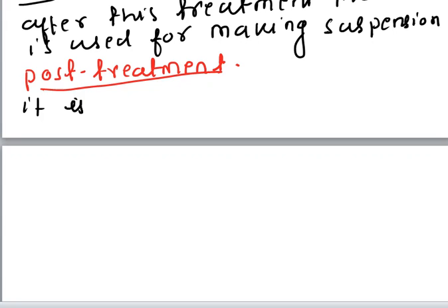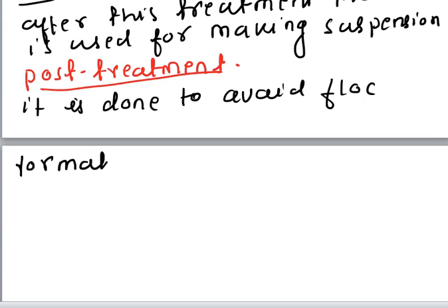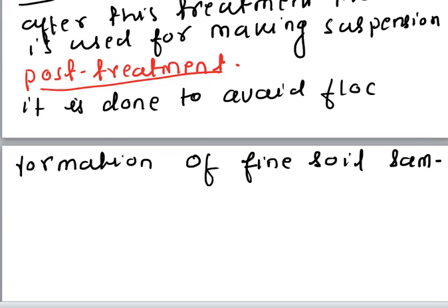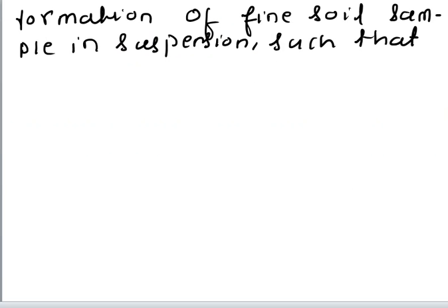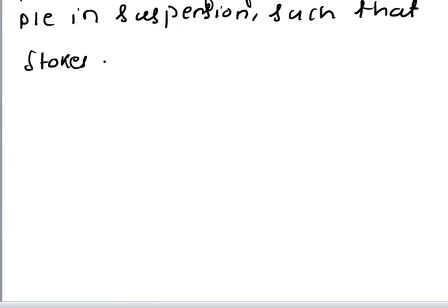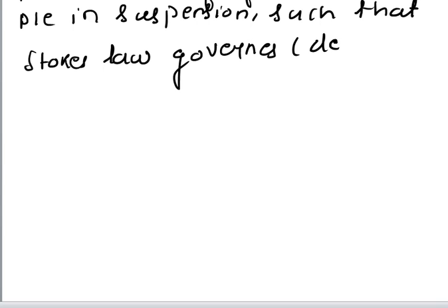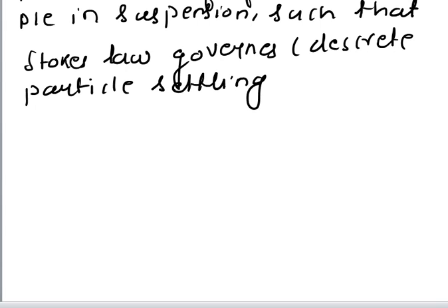So it is done to avoid flock formation of the fine soil sample in suspension, such that Stokes law governs, that is discrete particle settling occurs.